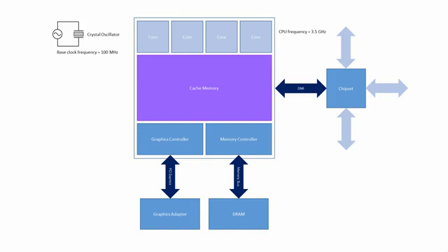If a CPU's frequency multipliers have been unlocked, then it's possible to change the way the base rate is multiplied up by the CPU. This is called overclocking. Be warned, however, if you're going to try this, you might consider upgrading your CPU's cooling system first. Even then, other devices in the PC might not be able to keep up with an overclocked CPU, which can make the whole system unstable.